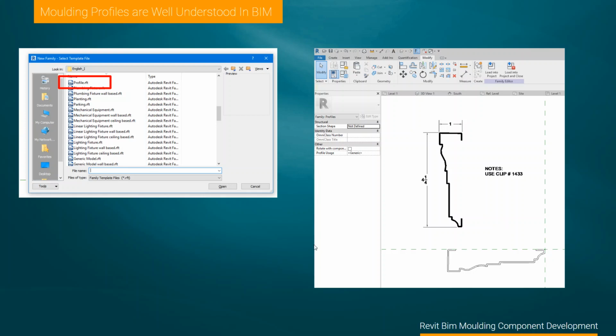So there's a little more explanation of that idea of doing profiles. Inside of Revit, whenever you want to extrude a surface along a path, you start with a profile. Revit has a whole host of different kinds of profiles for whatever technical applications, but there's a generic profile element that's used for actually a majority of the things that we're going to discuss. And I'm showing how I've opened one of those in that family environment. I've imported the DWG file that was available from your website, and I then took it and rotated it and cleaned it up so that it would be available as a clean profile.